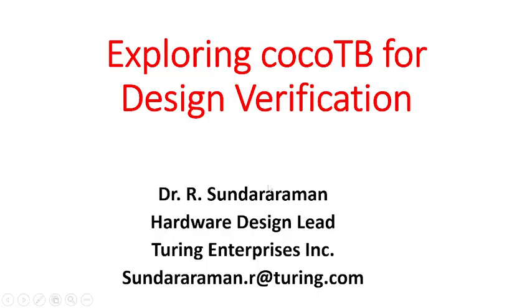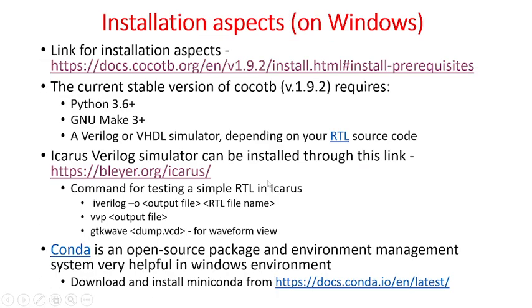So we know that we have now installed the Python platform, which is already there. GNU Make is there. Now we have iVerilog, the Icarus tool, and then GTKWave. Then Conda, that is Anaconda. We have a Miniconda setup, because it's an open source package for Python related environment management.